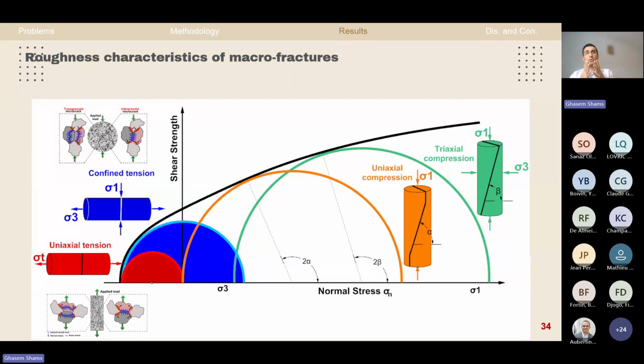Therefore, we will have stronger microcracks. They need more energy, more work, more load to shear. And therefore, the presence of more shear microcracks with higher shear strength during the failure process of the Brazilian specimen increases the overall tensile strength of the specimen of the same material, like granite.